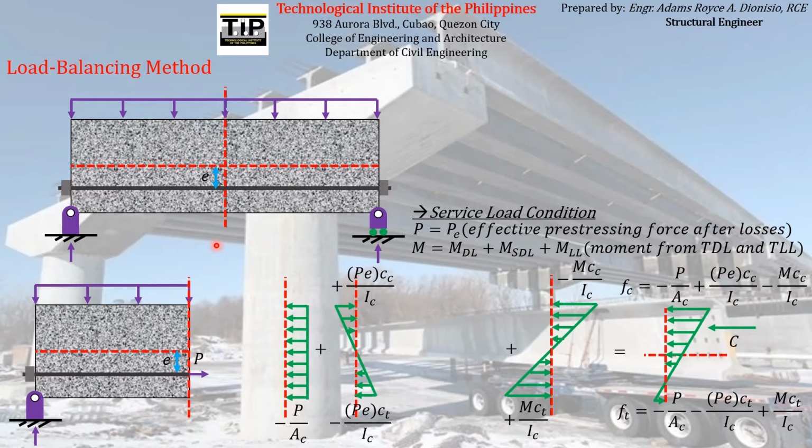We already know that for a simply supported beam which supports a uniformly distributed load, the moments induced inside the concrete element vary from 0 at one support to a maximum value at midspan, and then go down again to a value of 0 at the other end.